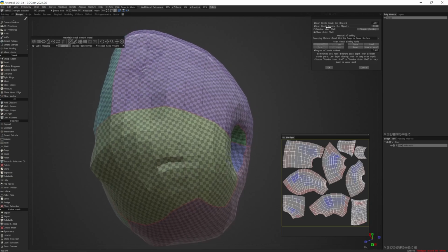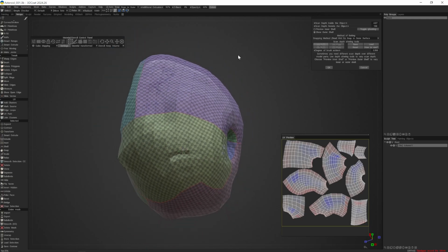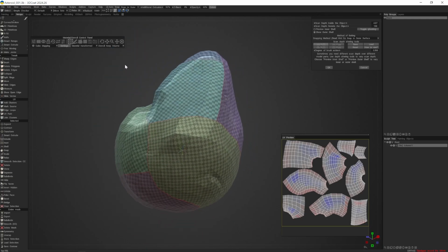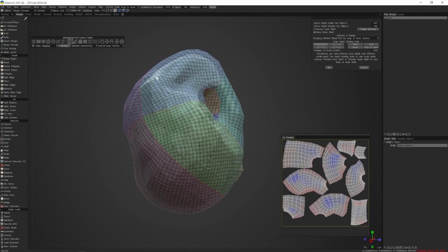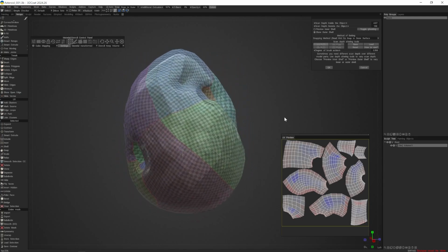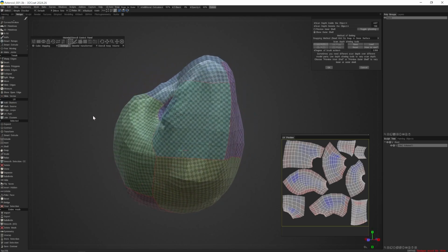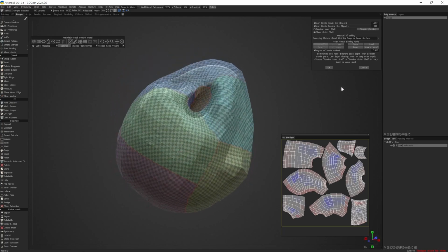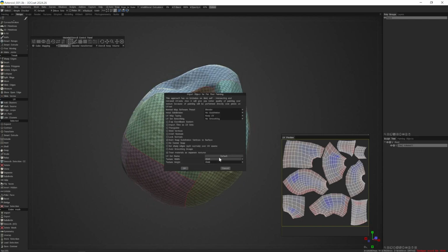but it's better to avoid it in the first place. So here's my outer mesh. Again, same thing. I want to make sure no parts of my underlying sculpt mesh are visible or poking through this outer mesh, this outer bake cage. And it looks like nothing is, so I'm good. I'll hit OK. It's going to prompt me and ask me what level of texture density I want.